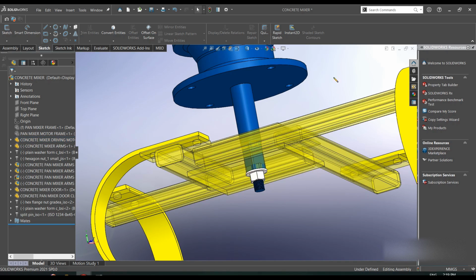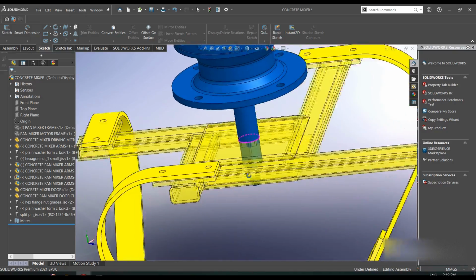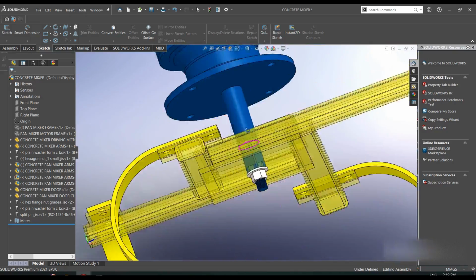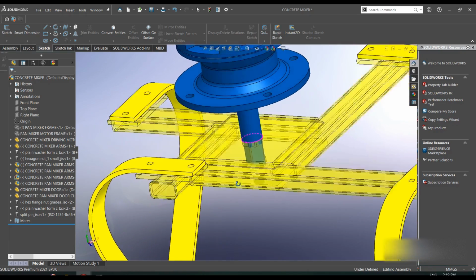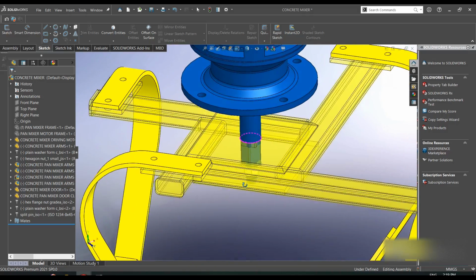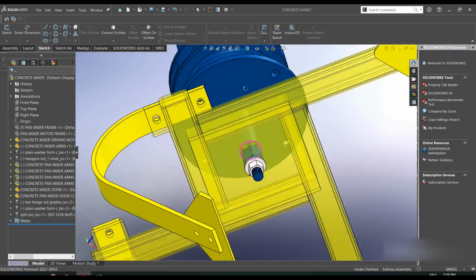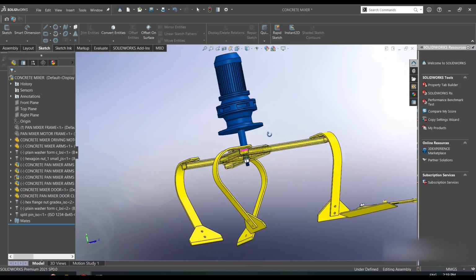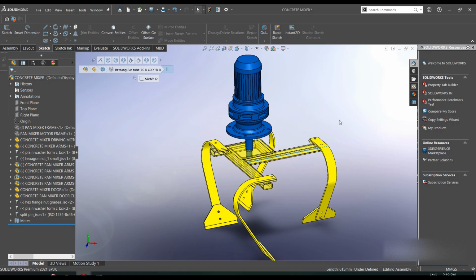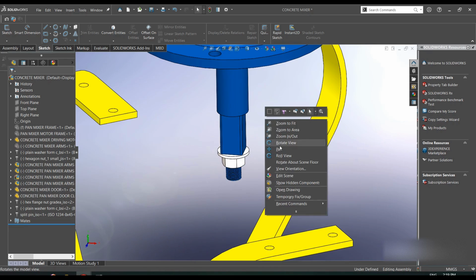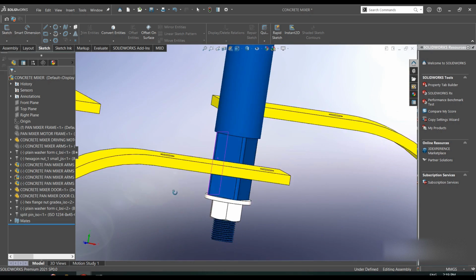In some cases you might use a keyway, but I think this is better than a keyway because here you guarantee that everything is firm. A keyway means that at some point it may wear out, but this is a bit stronger than a keyway. So instead of having a keyway, we have just a square shaft here.